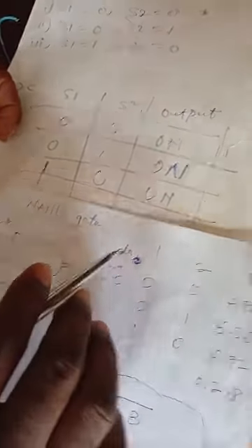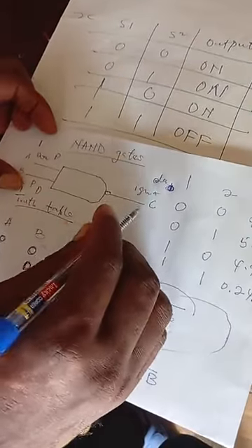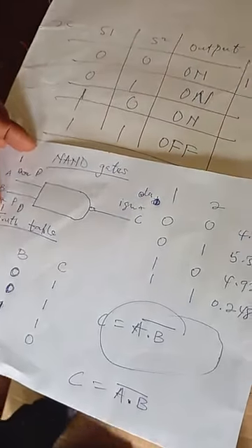It now becomes on. But whenever any of these is open, there will be an ignition. So it's only when both of them are now at 1, the door has been closed, 1, the gear has been put to park, 1, that's when this one would now go off. That's when you are going to start the car. That's the application of the logic gate for the new model of the car.